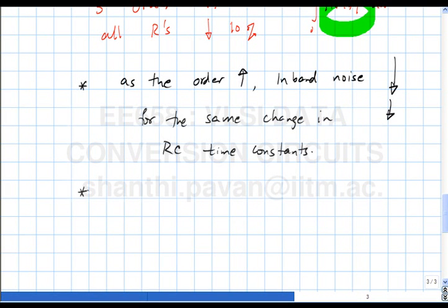Yeah, in a higher order system, the gain will show up as the ratio of components and hence should nominally remain the same. No, that's not correct. The gain will be of the form 1 over RC, no? So 1 by S whole to the power n at low frequencies.